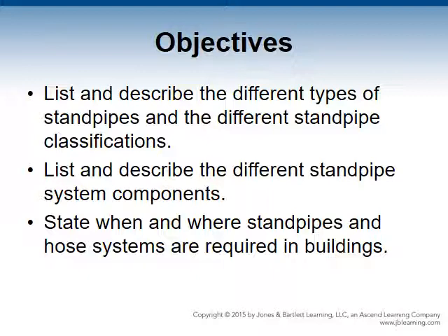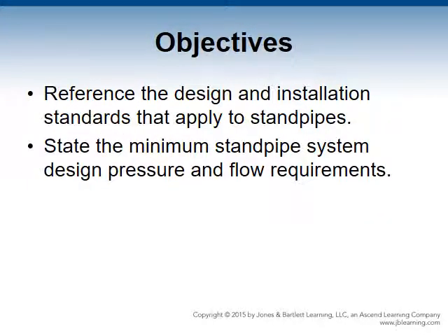List and describe the different standpipe system components. State when and where standpipes and hose systems are required in buildings. Reference the design and installation standards that apply to standpipes. And state the minimum standpipe system design pressure and flow requirements.